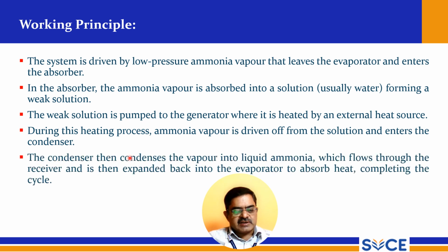The condenser then condenses the vapor into liquid ammonia, which flows through the receiver and is then expanded back into the evaporator to absorb heat, completing the cycle.